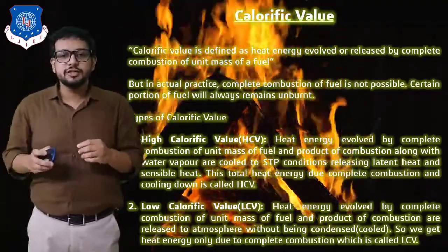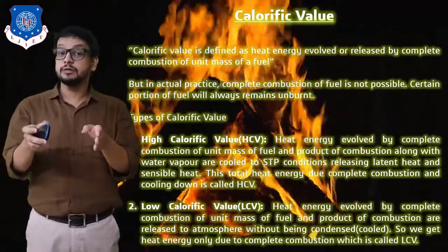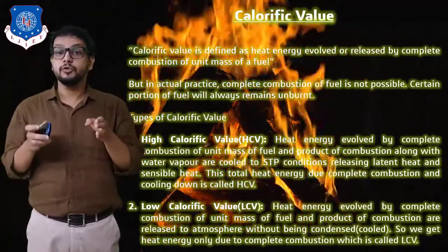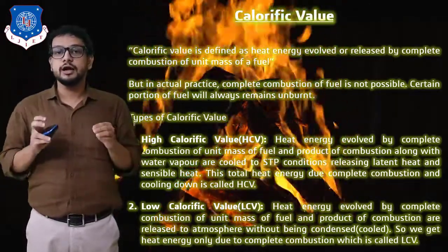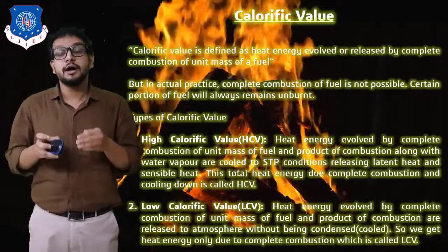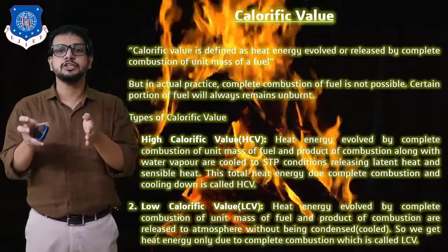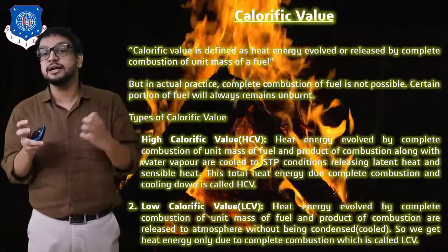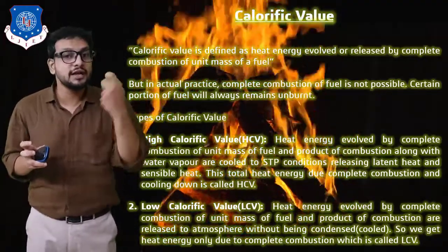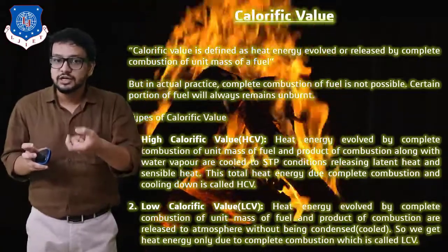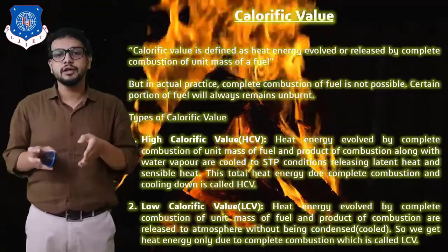As you can see on your screen, I have written the definition of high calorific value: heat energy evolved by complete combustion of a unit mass of a fuel when the products of combustion along with water vapor are condensed or cooled down to normal condition, that is STP, standard temperature and pressure. Then heat energy will be released, both latent heat as well as sensible heat. So this total heat energy produced due to combustion as well as due to cooling down of water vapor contributes to the high calorific value.